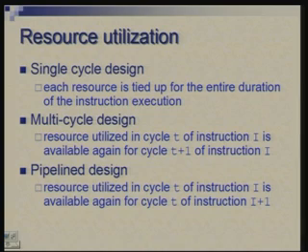In pipeline design, what we will try to achieve is something different, that a resource which is utilized in, let us say, cycle T for instruction I is after that free for the cycle T of instruction I plus 1. That means, if addition is done in third cycle of one instruction, that adder will do same third cycle addition for the next instruction.